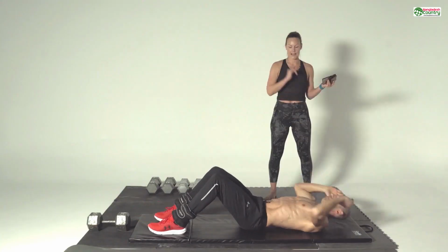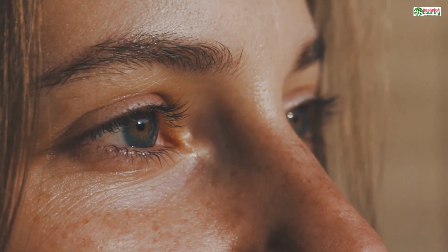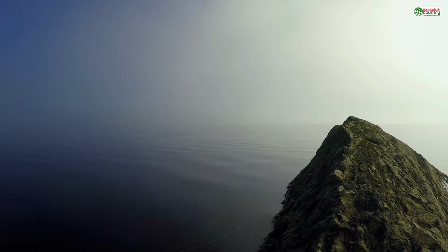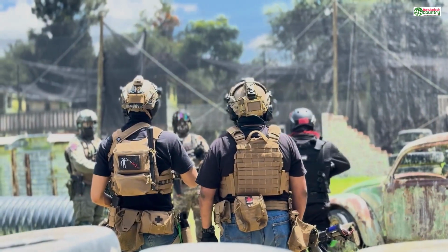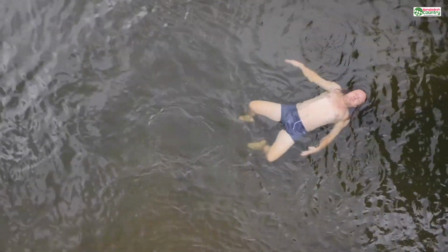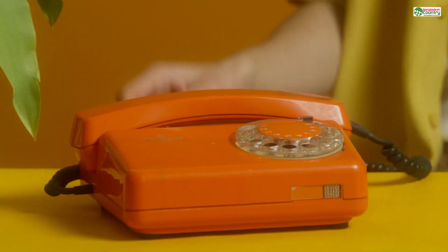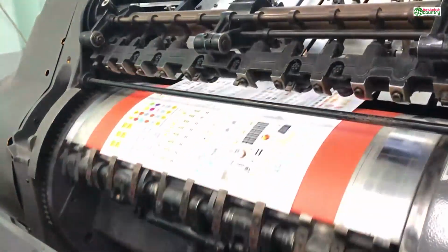But as you stare at your beautifully optimized model, there's a silent force waiting to ruin your print, a force that affects every single 3D printing technology: gravity. Your model has areas that stick out, floating in midair with nothing beneath them. These are called overhangs, and if you don't handle them correctly, your print will collapse into a stringy, drooping mess. The art of defying gravity is our next challenge.